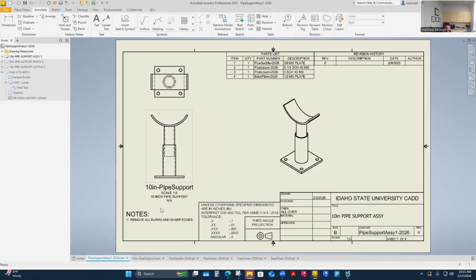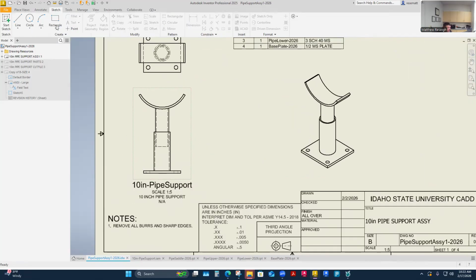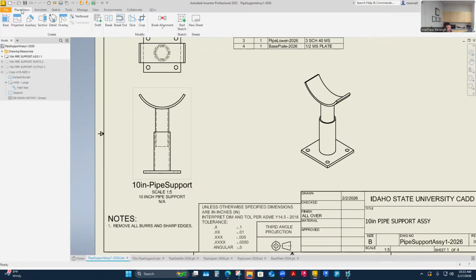Maybe I'll cut the section view before I move to the next sheet too, because it's a good one to practice here. I'll place my views, section. So I should be coming into this view. I want to take a section view of this view. I just want it to cut in here, so I think I have to cut this way. So I click there. I'm going to draw to about the center line here. Maybe I'll target that, cut into center. And I'm going to cut through here on center, but not click to anything.